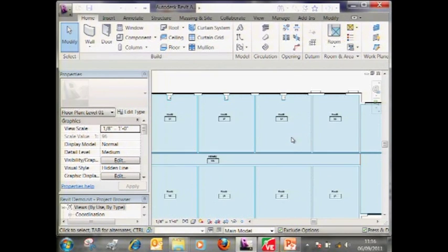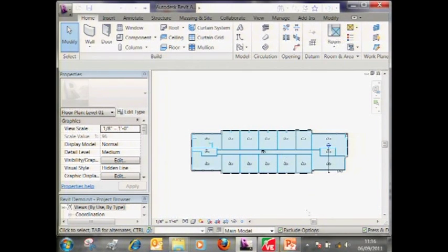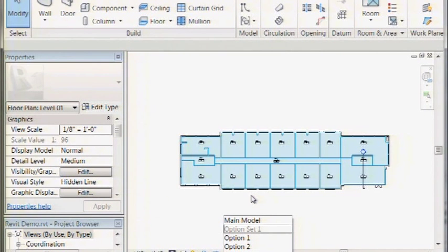But there are benefits for this, as Sarah was saying, where this model may not be completely done. I mean, we don't even have doors, we don't have a lot of detail, but in this case, I've actually included 3 design options. This is a great tool if you're working with architects to start off really early. You can set up 3 sets of design options. In this case, we have slightly different square footage, slightly different glazing ratios, and whichever one is going to be primary is going to be the one that's going to export. So you could say, give me 3 design options that you're looking at in the same file, cleaning it up once, and when you export it, I can set the different ones to primary.